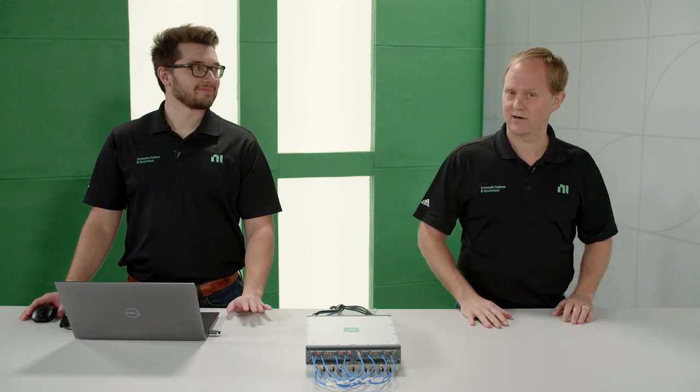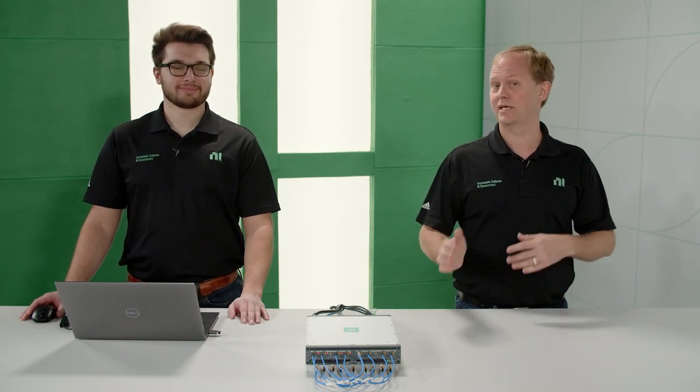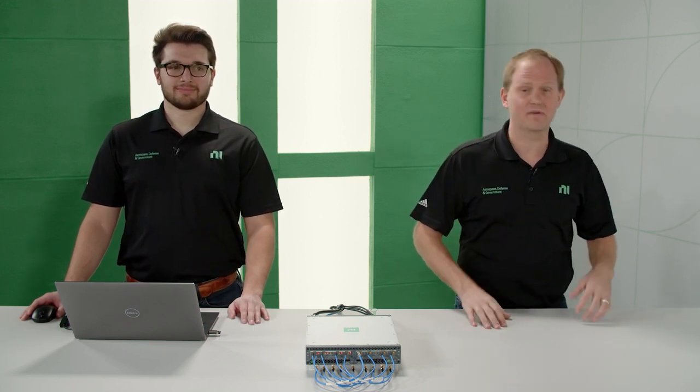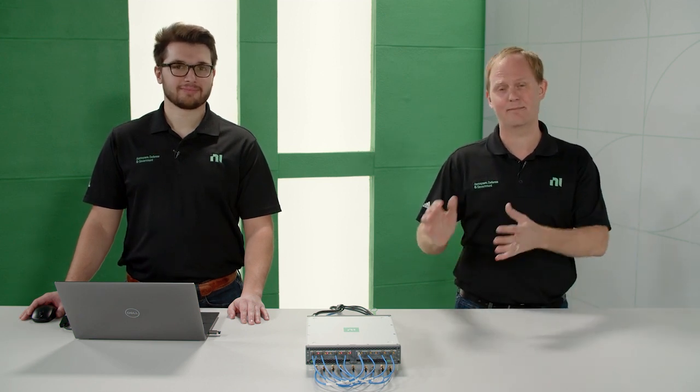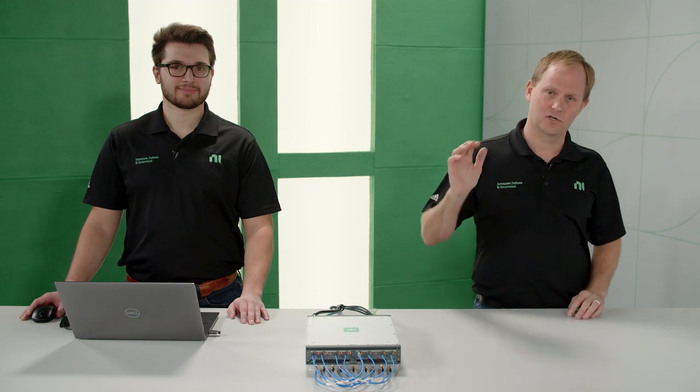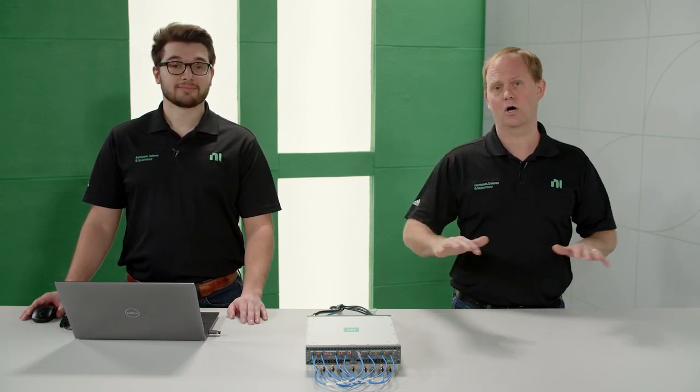This new software-defined radio is the widest bandwidth, highest channel density USRP yet. With 8 transmit channels and 8 receive channels and 1.6 gigahertz of instantaneous bandwidth, it's got a lot of capability packed into it. Being a direct sampled architecture, we're able to achieve full phase coherence across all 8 channels.